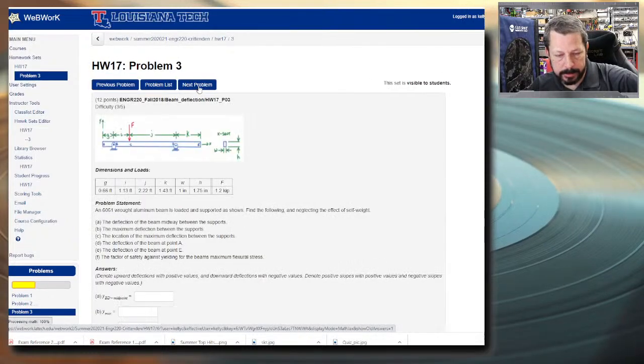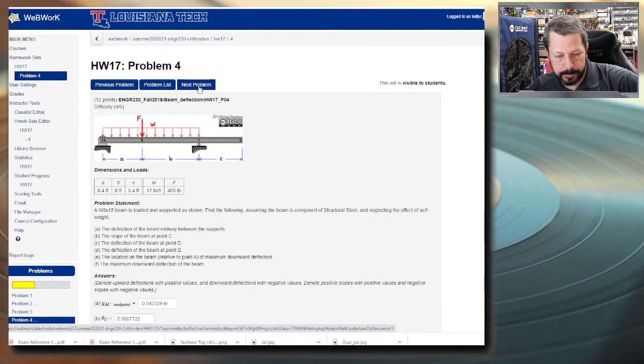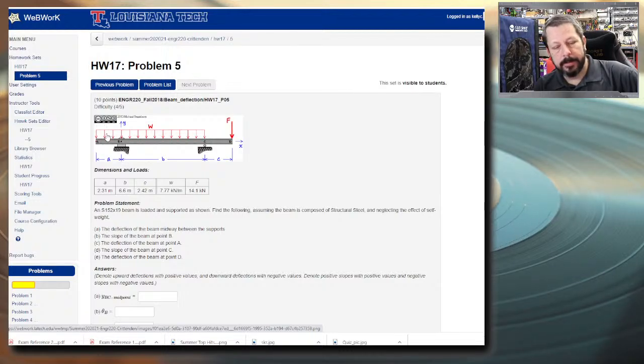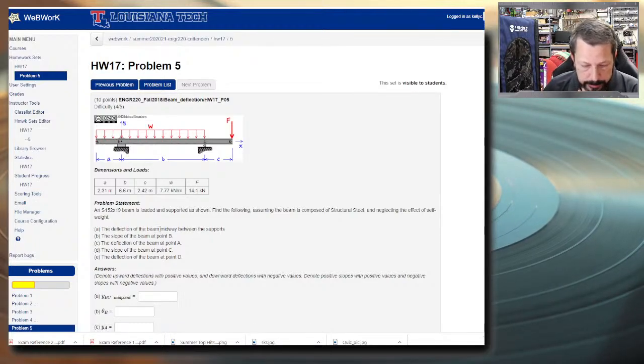This one that I was looking at just now has two of those. It has this exact same thing on this end, and then over here it's got a similar thing, except it's a distributed load. So for the distributed load, you have to lump it, and create the moment by the lumped load times half of A about B. So that would work for part A.